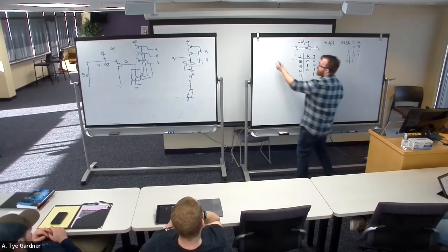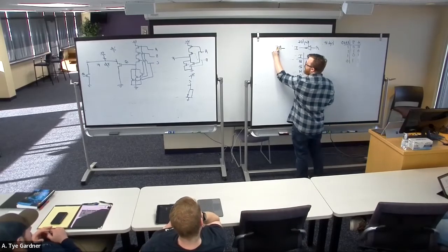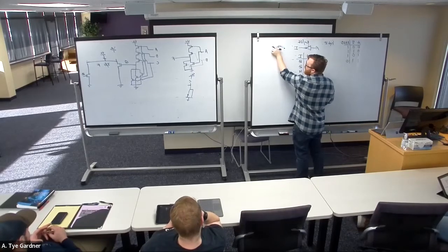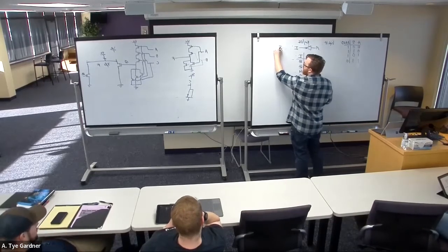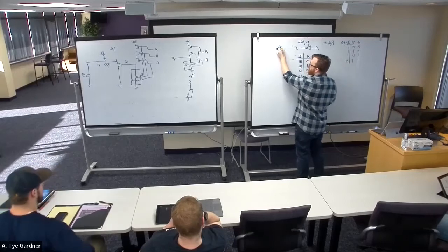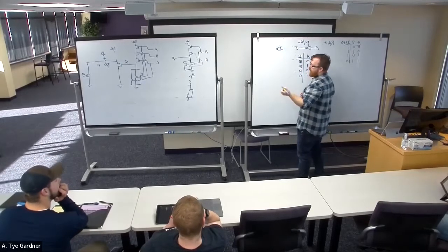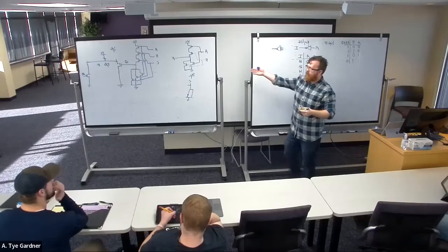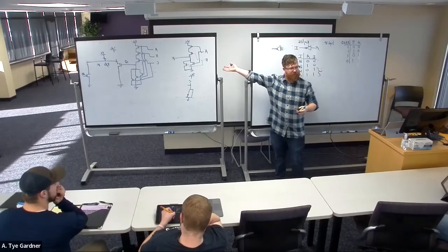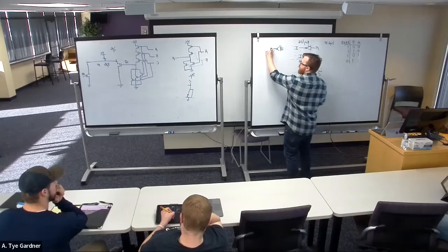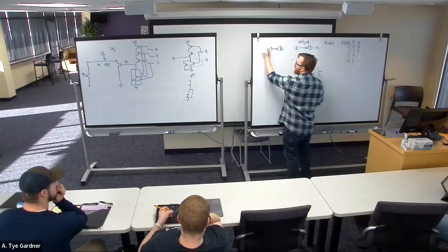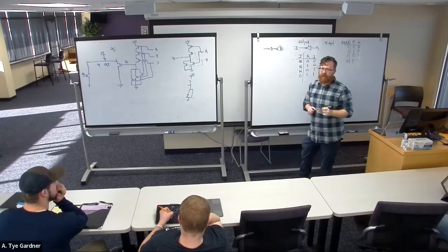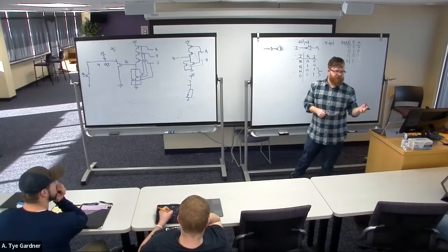You can have things like, this would actually make a lot of sense. Let's say I had an open drain NAND gate. A lot of times the way that this is going to get drawn is because the open drain part is actually kind of a different circuit a little bit. And so it's just going to use the advantage of saying there's a buffer there, and that buffer is going to have an enable.